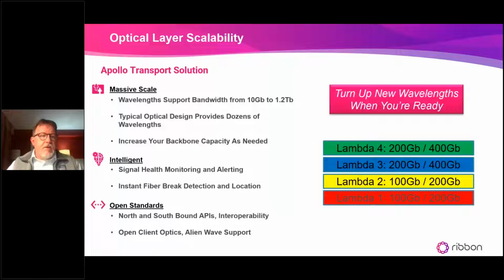So there's no need to roll a truck with an OTDR handset and interrupt traffic or lose any further time. What we do is simply turn on that OTDR, or what you would do is turn on the OTDR from your management console and then take an OTDR shot.